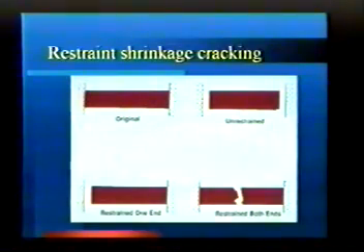All right, let's talk about the restraint. In concrete, if you pour concrete between two rigid, immovable objects, initially if you break it and allow it to be free from the immovable objects, it shrinks. All concrete shrinks. Yes, there's shrinkage compensating and all that other stuff. All concrete shrinks, as Alex had said earlier. And we get a gap at both ends. Now if I tie one end and allow it to shrink, it's going to shrink at the other end. But if I tie both ends and it wants to shrink, something's got to give, and it's usually the concrete. And here's what happens.